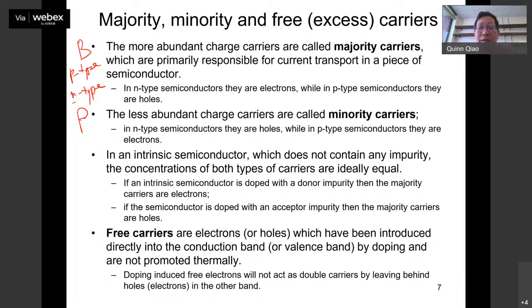Okay, so the definition here: whenever the silicon is doped p-type, you know that positive charge is the majority carrier, right? When you dope with n-type, you have a lot of negative charge, so negative charge is the majority. If you identify one as majority, the other one will be minority, right? So here, if you look at this n-type semiconductor, the dopant is the majority carrier, electrons, so the minority carriers will be holes, okay?